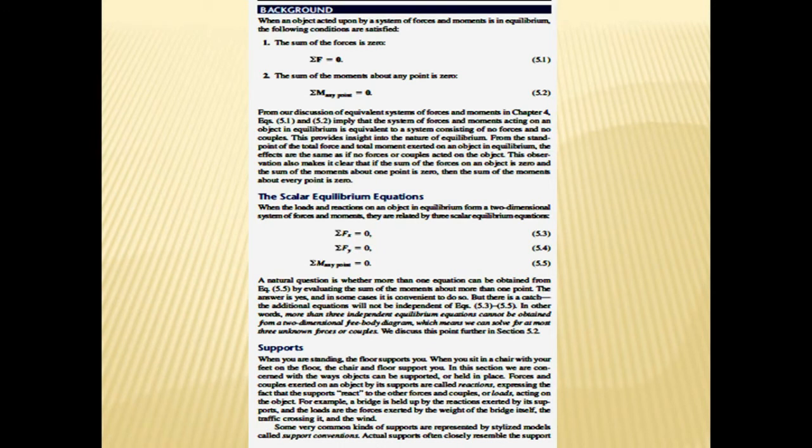Okay, so this is what it's trying to say: if on a body we only say that the summation of forces acting on the body is 0, and we do not use that the moments equal 0, then the body may be in equilibrium, or it may not be in equilibrium. But if the moments acting on a body are 0 and the forces acting on the body are 0, then we can very safely say that the body is in equilibrium.